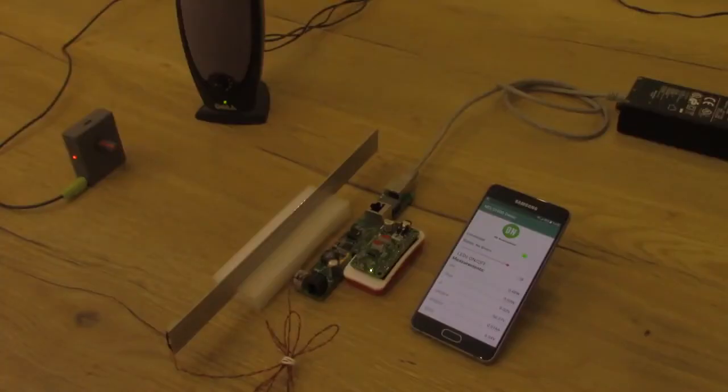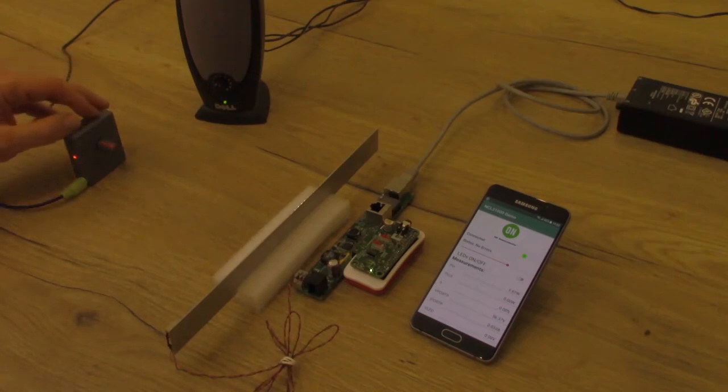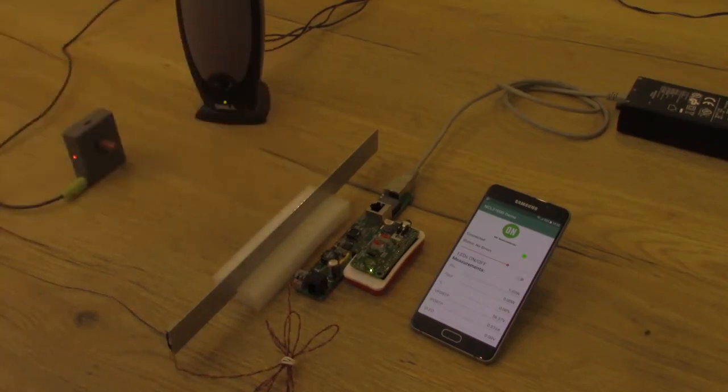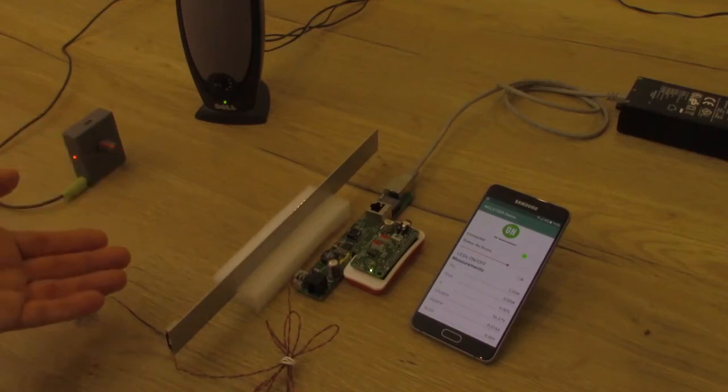To demonstrate visible light communication, we have added 2 elements to our setup: a small receiver and speaker system. Because of the high linearity of the LED driver input and its high bandwidth capability, we can modulate audio on top of the LED brightness. You can think of it as a simple amplitude modulation, where visible light is the carrier and the audio is the modulated information on top of it.